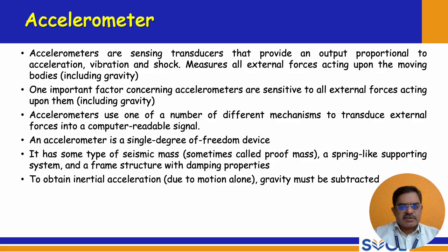So next is the accelerometer. Accelerometers are sensing transducers that provide an output proportional to acceleration, vibration and shock. So shock is also one of the measurands that should be considered. It measures all external forces acting upon the moving bodies, so that should include gravity also. Then only this can be called a seismic device. One important factor concerning accelerometers is that they are sensitive to all external forces acting upon them.